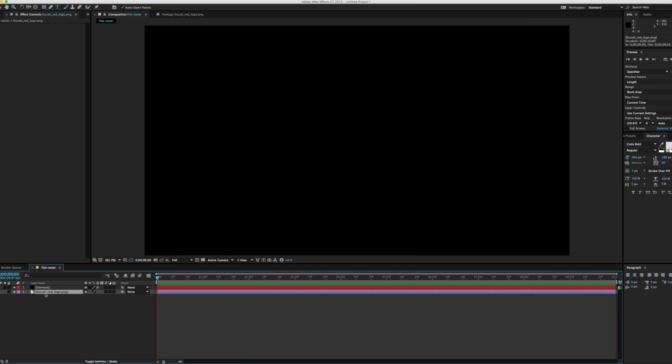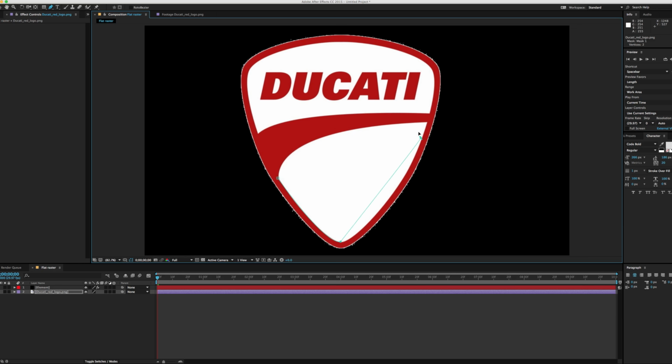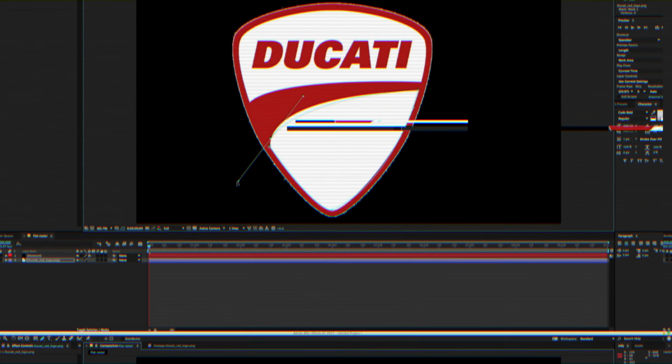The reason is because there's not any information that Element can use. So what do I do to get around that? Well, I'm going to turn this back on. And we just established that we can only use text or masks to use this in Element. So the easiest way is to just draw out this shape or break it down into these different shapes using my mask tool. So I'm just going to very quickly create a not so perfect one here just so we can take a look at what this is. And I'll see you in just a second.